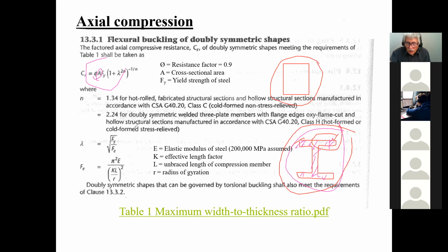But for sure, if you want to design with metal studs, you got to go to S136. That's the standard, because the material is so thin that it's all the local weaknesses that control your design. And that's why it's a completely different animal and a completely different standard and completely different formulas. Very similar to these, but very, very more complicated. I design steel walls, but because these things are so thin, it's just sheet metal that's been bent into these shapes, these become very local weaknesses that control the design.